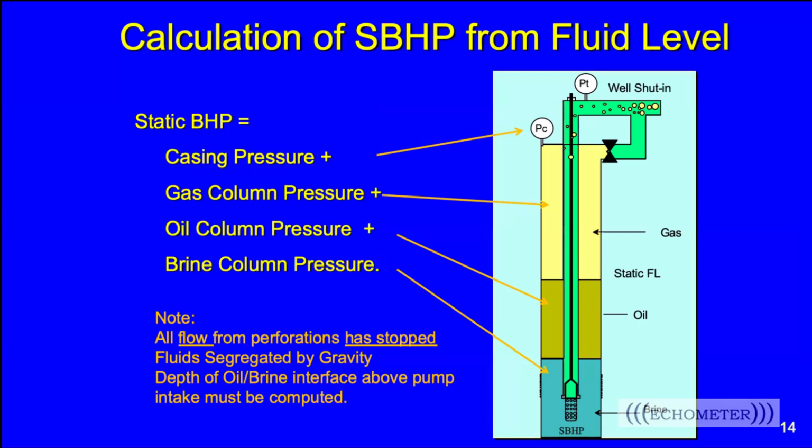So again, this has to be when all flow has stopped from the reservoir, the well's shut in, and it should be a quiet, stable environment. So in this case, we probably will have a lot easier time obtaining a fluid level measurement. We probably don't have to put as much gas on our gun to shoot the fluid level because it won't have the noise from the gas production coming up the well.